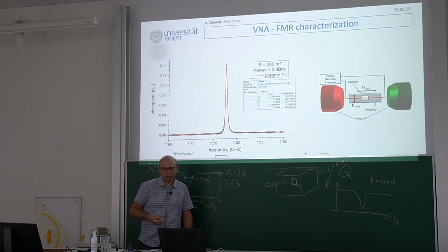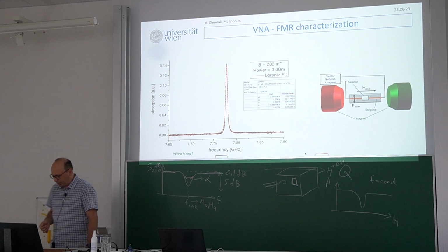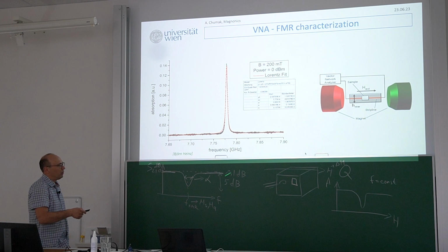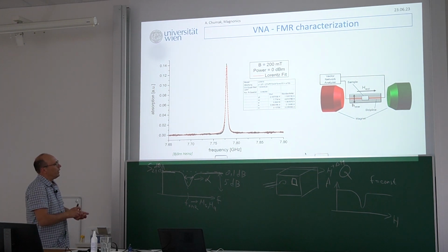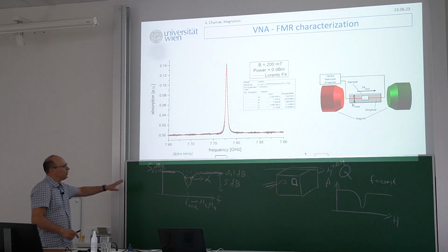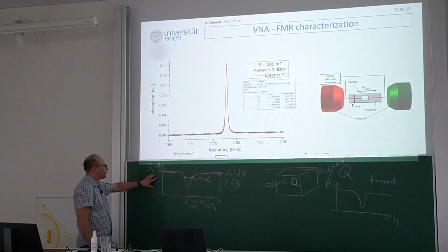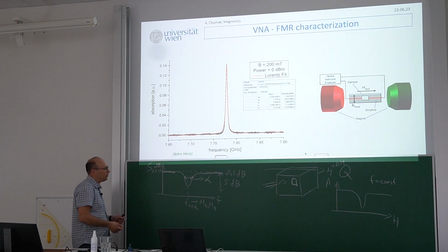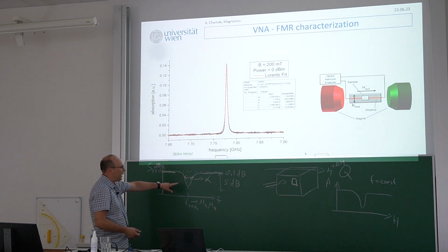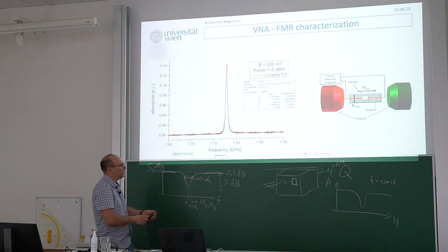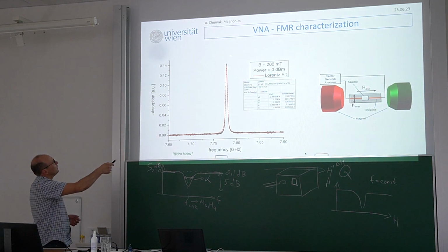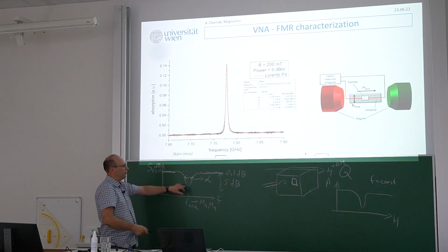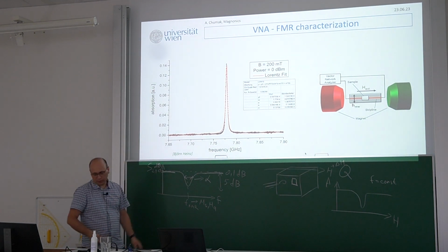Very, very small signal, which you will hardly see without subtraction of the reference signal. Therefore, always be careful how large this absorption is. And then, when you have the S21 parameter, in the simplest case you can just subtract this. If this is the maximal absorption, you can normalize this to 1, or just some arbitrary unit, so more or less you need to invert it in order to measure absorption, or 0 minus this one.